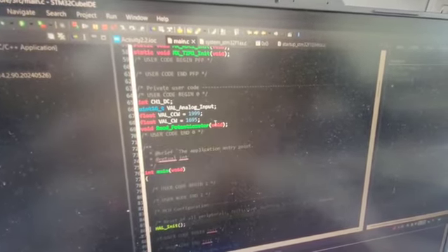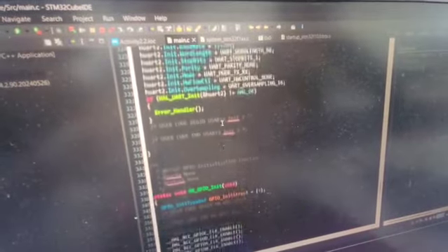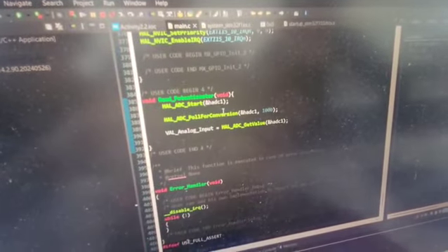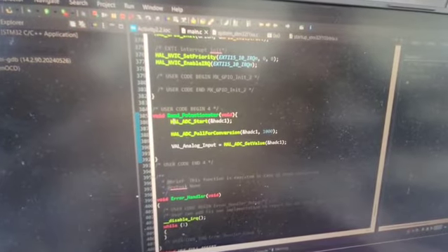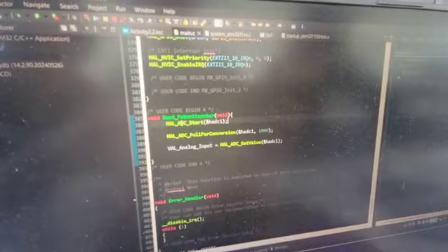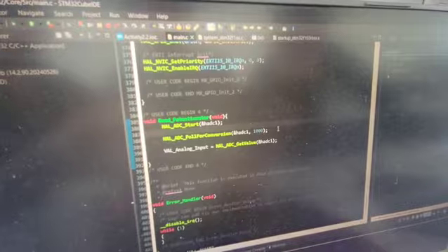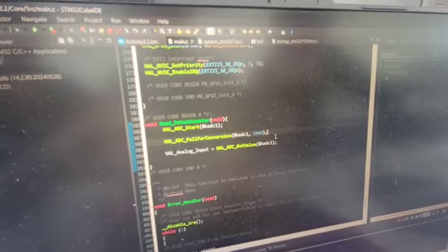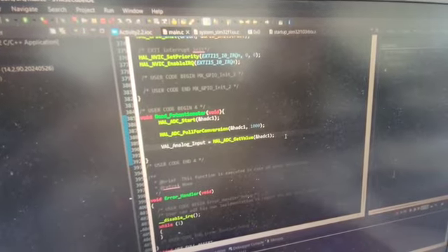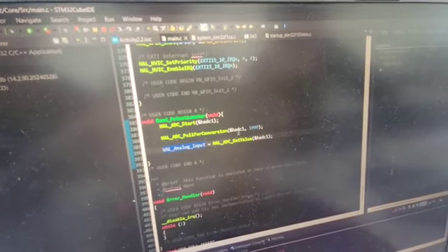And then the read potentiometer function, that is described here below. At first, it starts and it takes the reading from the AD converter. Then it proceeds to make the conversion, and it then gets the value and it stops. This value is taken in this variable for making debugging easier.